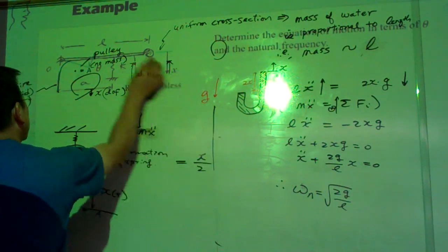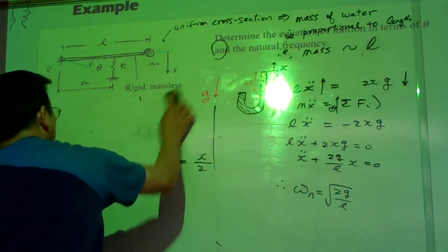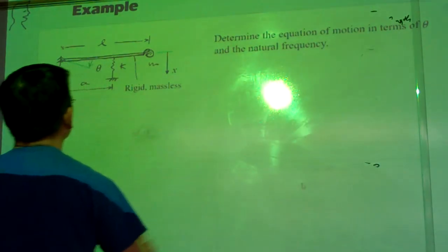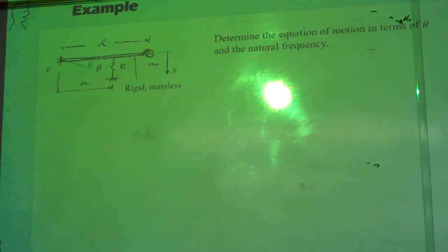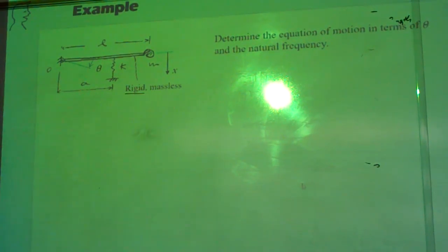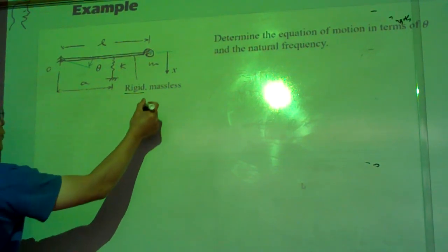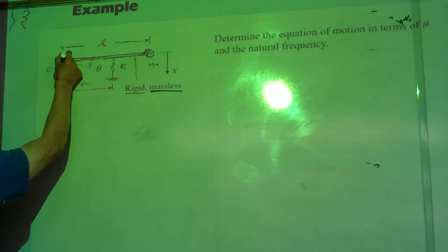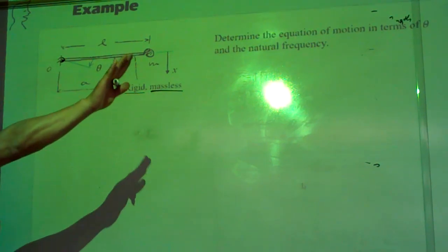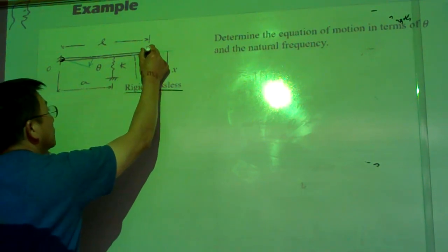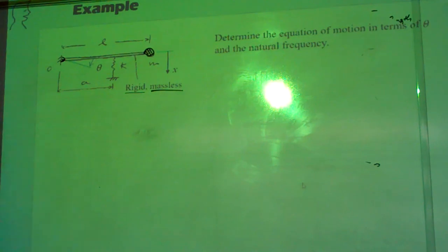And we can continue to take a look at another example here. That is the beam attached. So basically for this one, you can see this is the beam, and for this case, right now we assume the beam is undeformed, rigid, that means no elasticity and no mass, so we don't consider its contribution to the vibrations. And this is a pivot here, so basically the beam is free to tilt this way. Okay, so the only mass is from the end here.